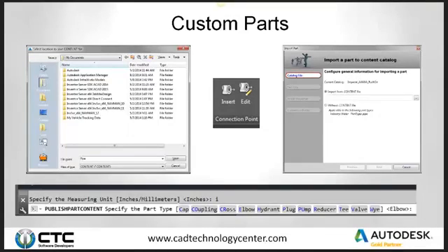I have one built up relatively quickly, and I'm going to demonstrate how to take that solid and define it as a pressure pipe network piece. And it's just simply in the middle, you have connection points. We build our part. We'll add connection points to the object. The first connection point will become where your part will connect to your network that's already existing in Civil.